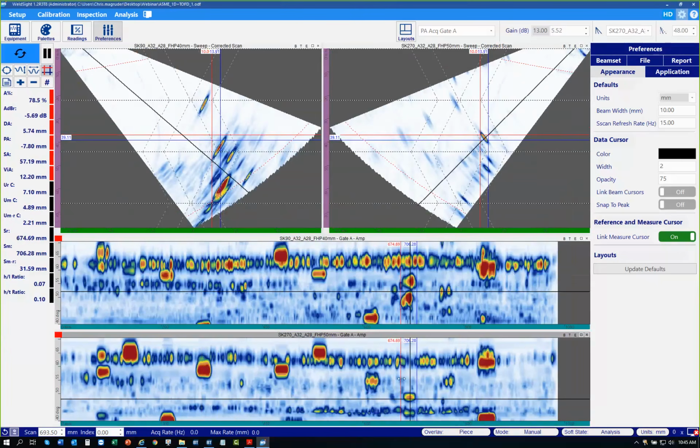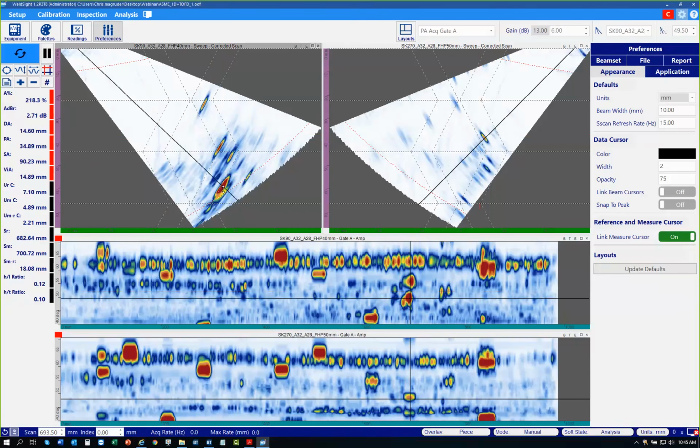And you notice the length of this here is going to be a little smaller than the length here of the other side, and we'll talk about that. So what's happening is this has perfect orientation right into the face of the weld. But we have very good supporting information here on the same flaw. We're bouncing off of the ID into the cap right here, which is this area here. Then we're bouncing off of the cap into the far side lack of fusion.